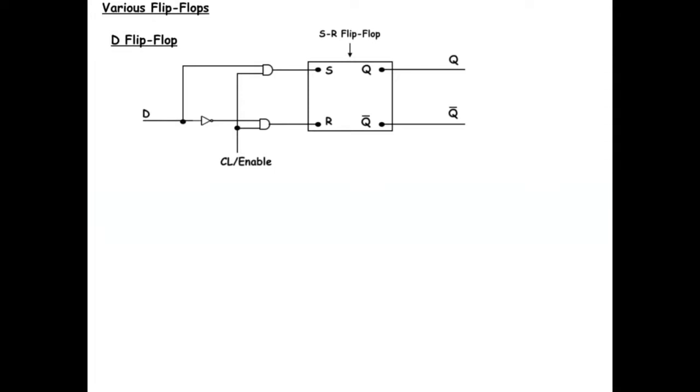You mentioned this yesterday, but I don't remember what exactly you said. Well, that's exactly right. When both are 0, nothing happens. And why is that important? Why do we need to have this possibility of nothing happening? What is the goal of having a flip-flop gate? When nothing happens, its previous state doesn't change. It's stored. Yeah, right. So we need to have this possibility of both inputs 0 in order to preserve this previous state until we are ready to change it.